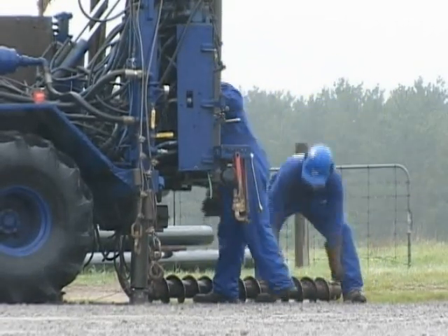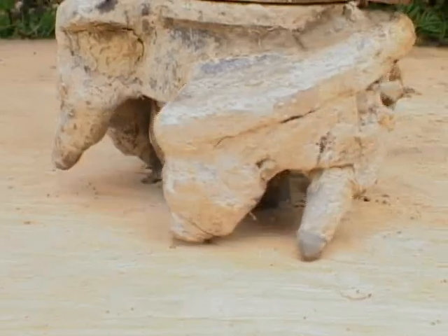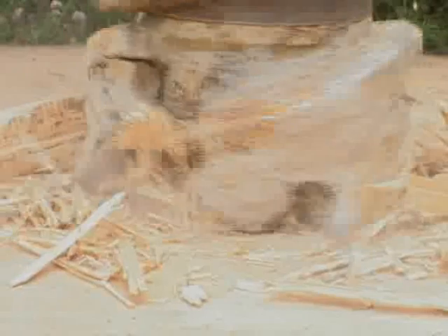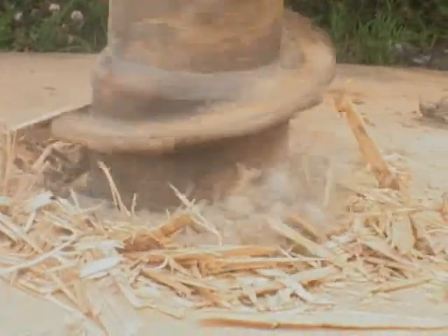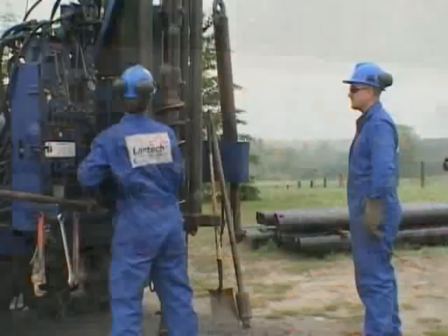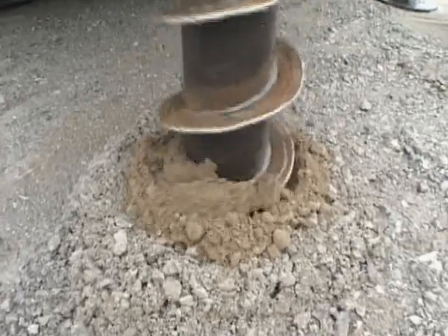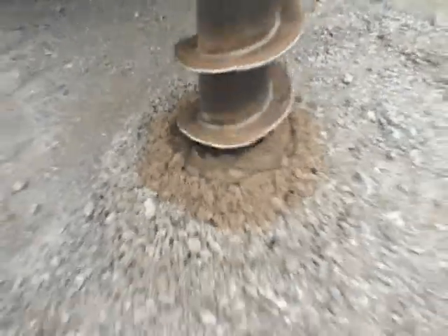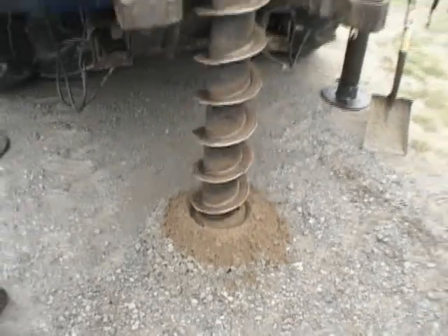The lead auger includes a pilot bit, which utilizes rotary cut action. The lead auger cuts the material, transferring the material up the flights of successive auger sections to the surface. No flushing media or drilling enhancements such as air, water, or fluids are used. This ensures true representative samples are obtained.